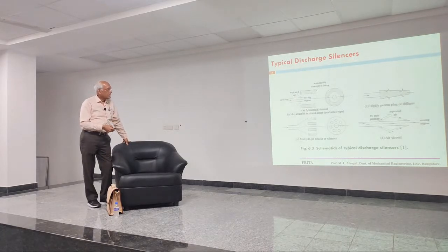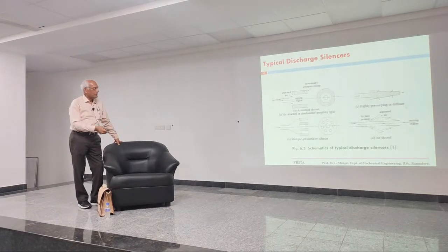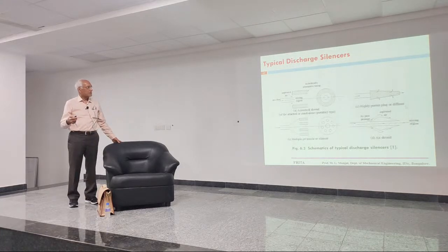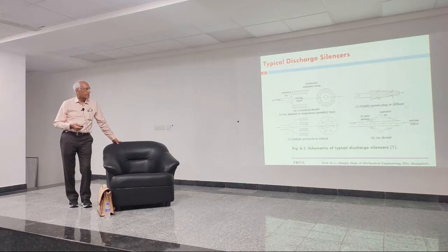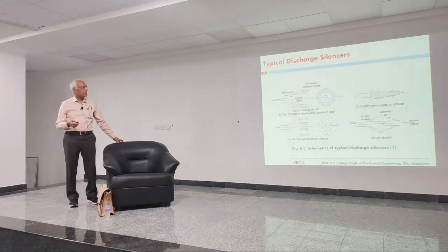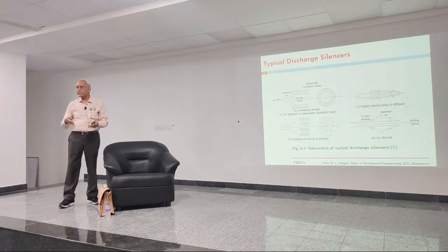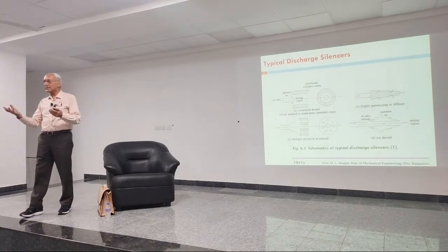You see now, this is, let's say, a jet coming out here, and this is the mixing region where most of the noise is produced. So you have around it a kind of acoustical shroud. So the net result is you are not disturbing that jet at all, but at the same time noise will be reduced. Okay, and this acoustical shroud generally is portable. I can just tell you it's very simple.